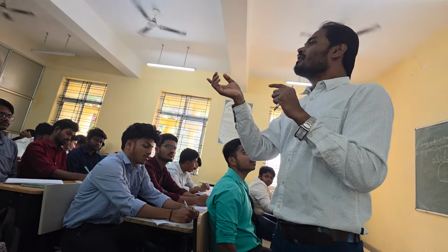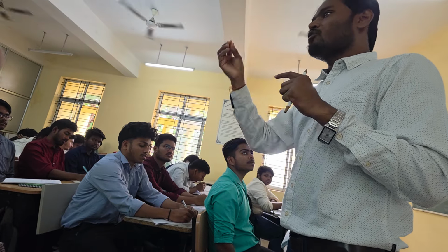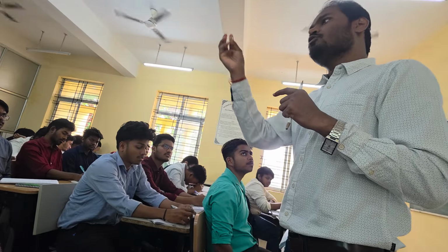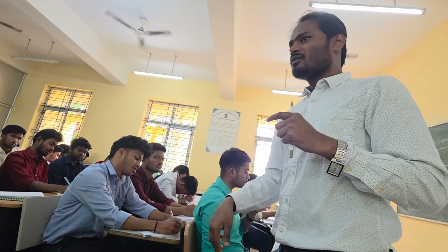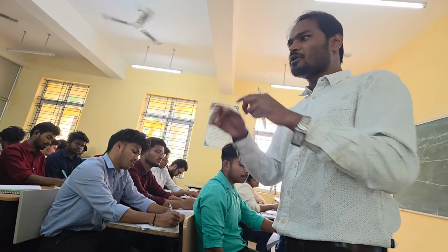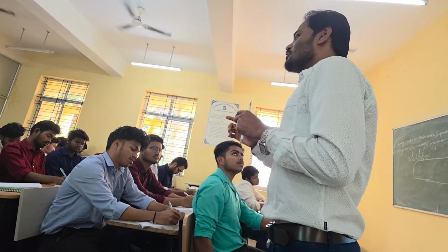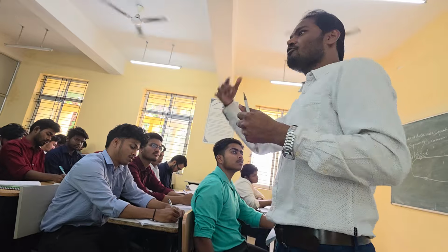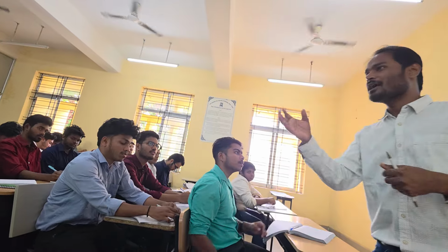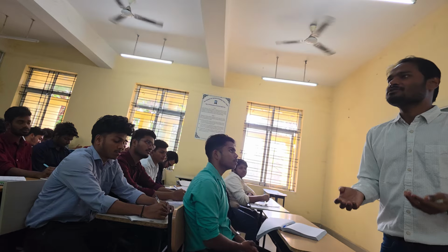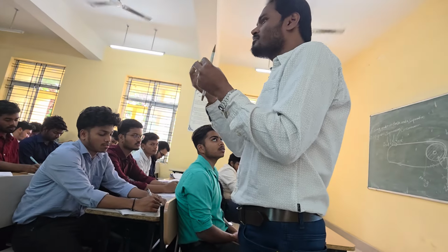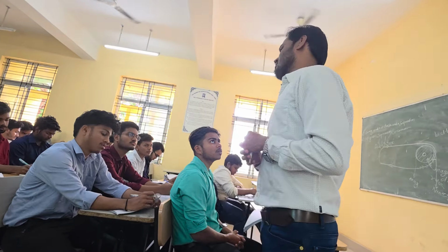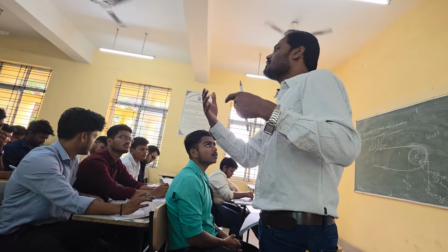And similarly, for moving down of this molten metal and molten slag, you also need this permeability, means voids through which it will go down. It should not stay up, it should go down and it will move to the earth at the end. So if you feed pellet and if you feed sinter, which one is better then for getting good permeability? Pellets obviously because they are uniform size, very good uniform size. So you will get uniform permeability. Maybe the required permeability will be also more.